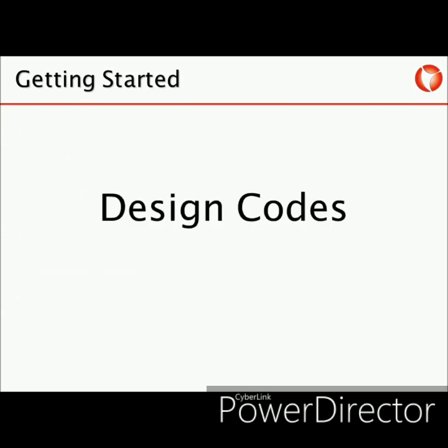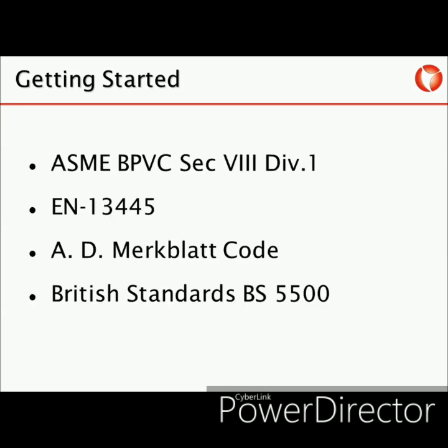The purpose of using design codes is to avoid disasters that can affect humans. Therefore, they comprise a range of experiences and good practices. Different pressure vessel design codes can arrive at different resulting wall thickness, yet having equivalent degrees of reliability. Provisions of a design code are an interrelated set of design, fabrication, inspection, and testing requirements. For example, the use of a higher design stress might depend upon use of a stringent material, analysis, examination, and testing requirements.